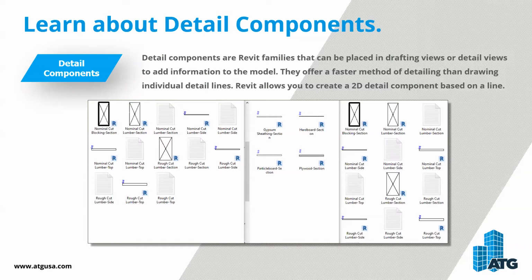So detail components are Revit families that can be placed in drafting views, and they come out of the box from Revit, and you can also download a variety of detail components to work with the material you're looking for. And you can also create your own if you're capable of creating families. They're actually very easy to create, primarily just dealing with lines, varying line types, and then of course your filled regions.